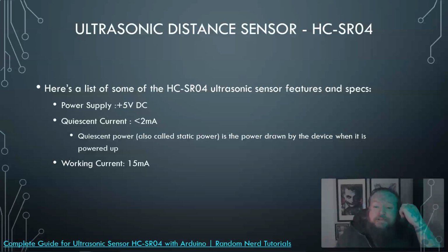Most times with these sensors, start looking up, okay, what are the power requirements of it? Are there any spec sheets or data sheets, as they're called, talking about this? Or are there even just posts on other websites where people have talked about this? I can get a rough idea. And going deeper, if you have more experience with electronics, you can start using different meters to measure the actual current requirement of this device in different scenarios, and do your calculations there.